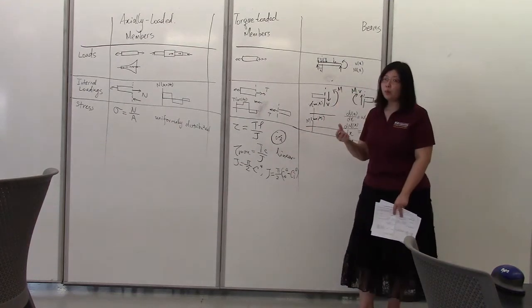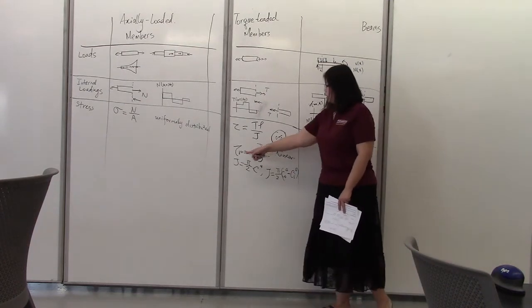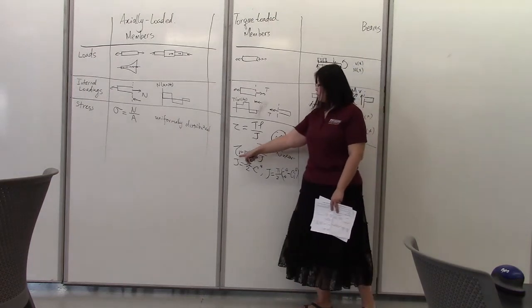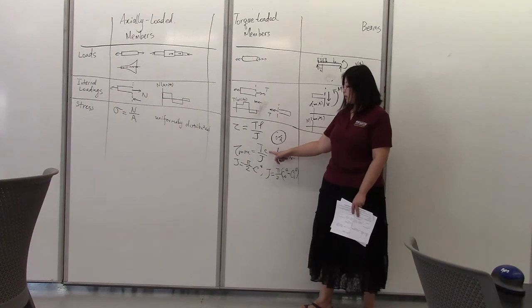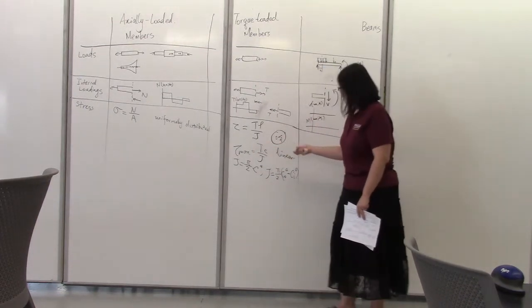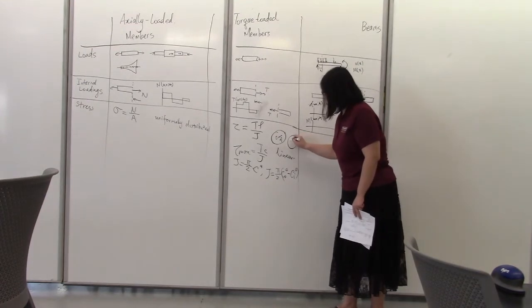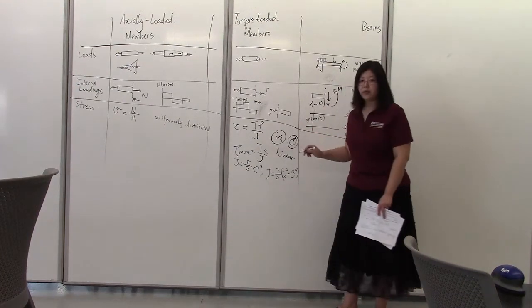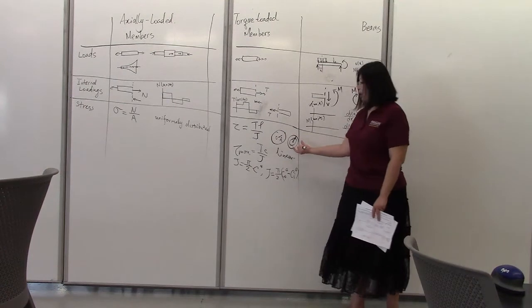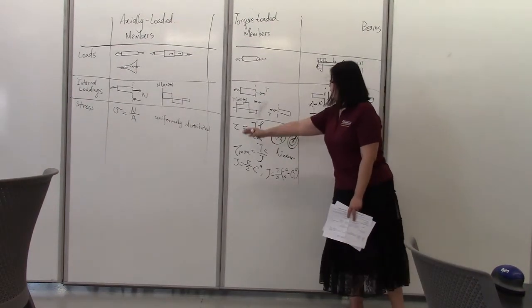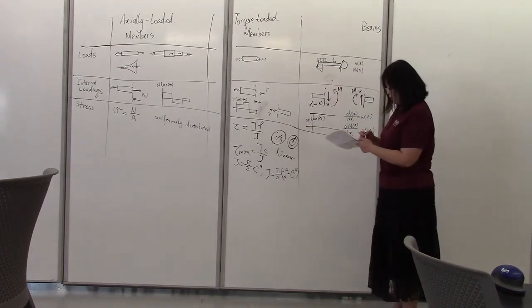And for a hollow bar, the maximum shear stress also occurs on the outer surface. Therefore, when you use this formula, tau maximum, your c is just the outer radius of the bar. That is where you have the maximum radial distance from the center to any point, which occurs on the outer surface. Therefore, maximum rho for a hollow bar is also just the outer radius. So that's the stress for torque-loaded members.